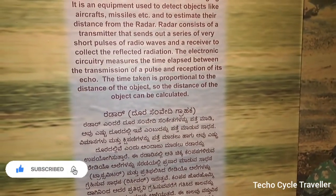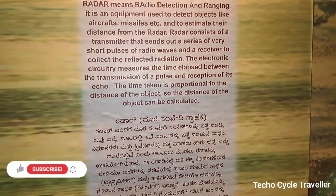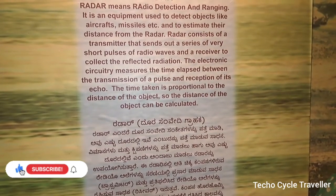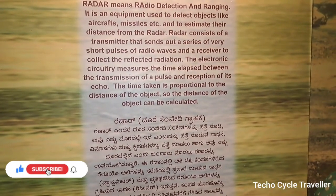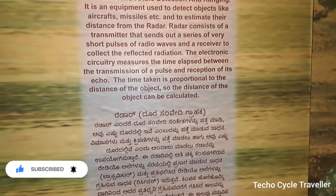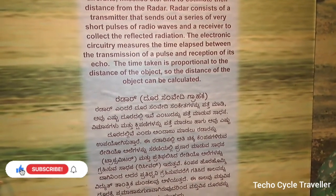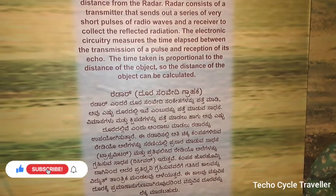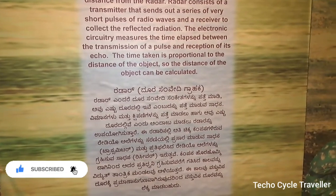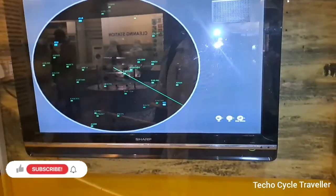Radar means radio detection and ranging. It is equipment used to detect objects like aircraft, missiles, etc. and estimate their distance from the radar. Radar consists of a transmitter that sends out a series of very short pulses of radio waves and a receiver to collect the reflected radiations. The electronic circuitry measures the time elapsed between the transmission of a pulse and reception of its echo. The time taken is proportional to the distance of the object, so the distance of the object can be calculated.